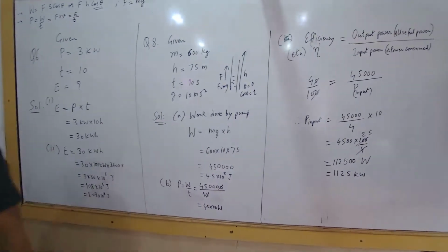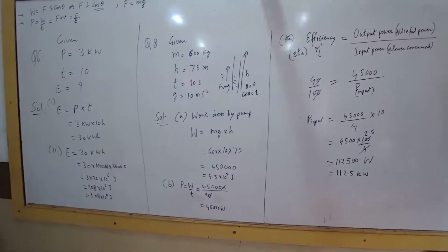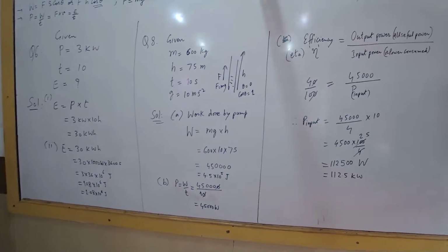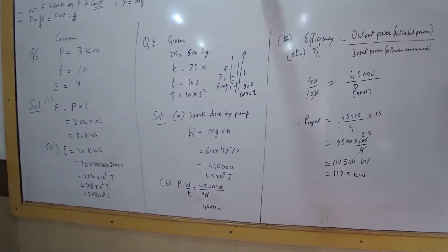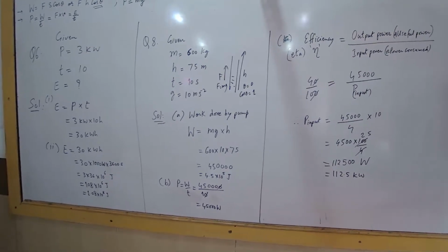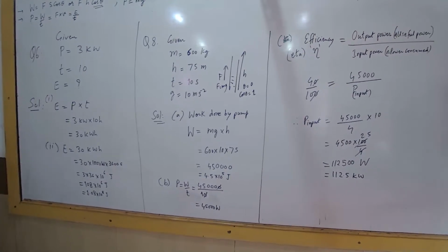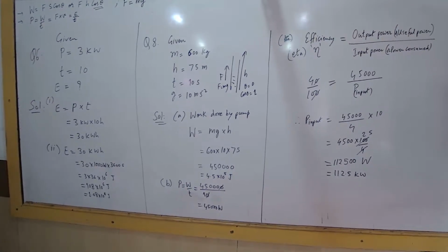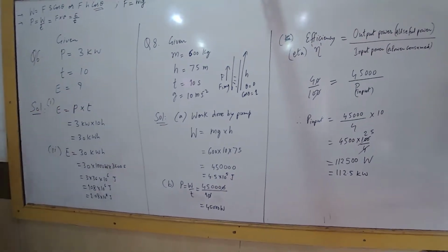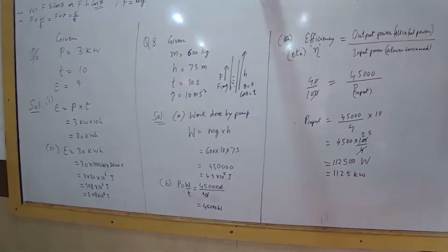All questions answered? Do you have any question? Power input is the actual power consumed, but you are not getting the full work. You are getting the work after the wastage, because every device has some power dissipated as heat. When the motor is running, it is not only delivering the lift of water. Water gets heated, so that power is wasted. That is why efficiency is never 100%. Some of it is wasted. In the machines chapter, this concept will be cleared for you.